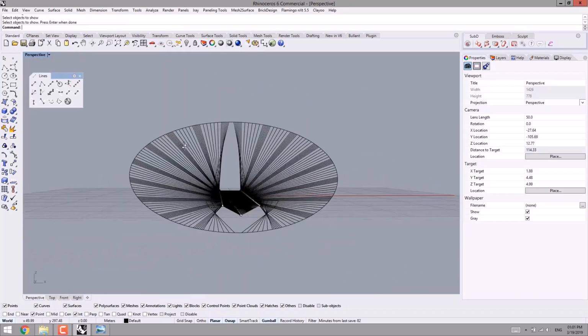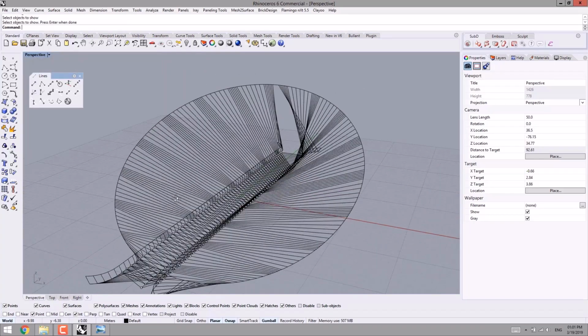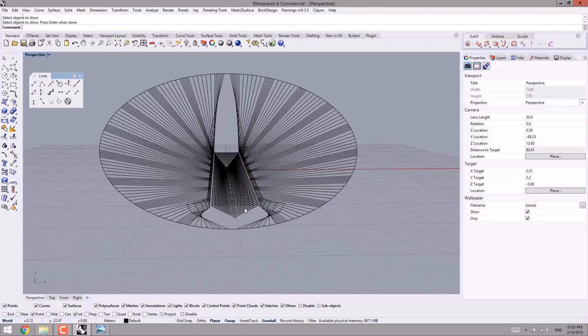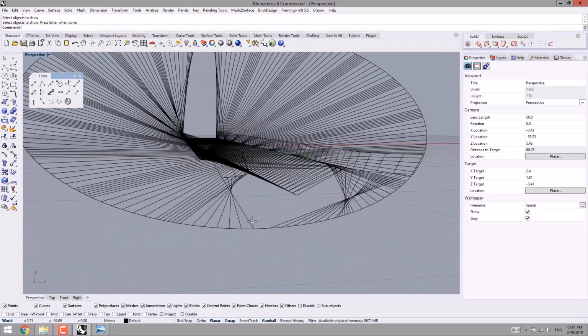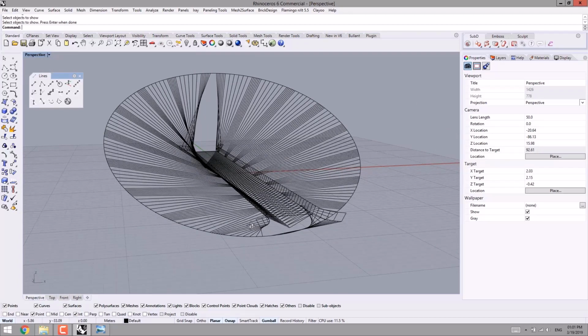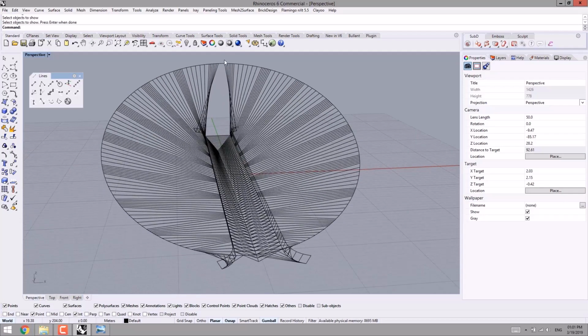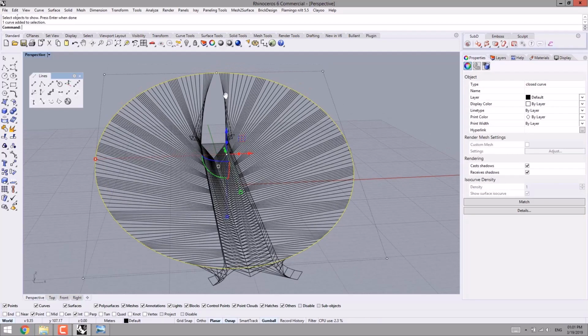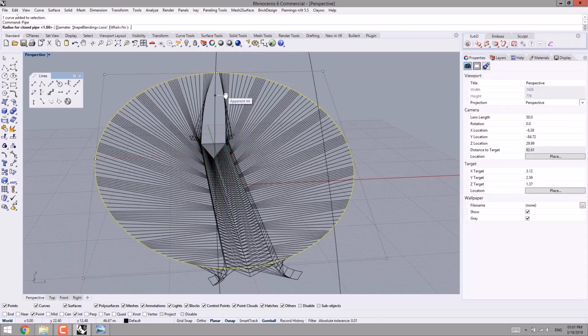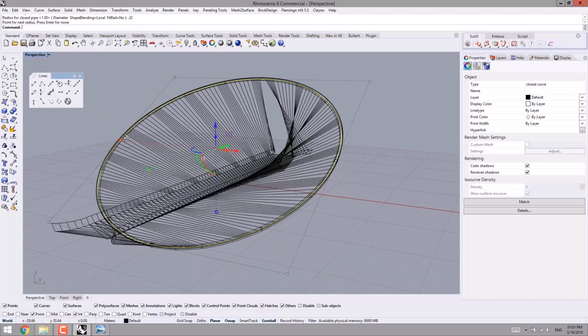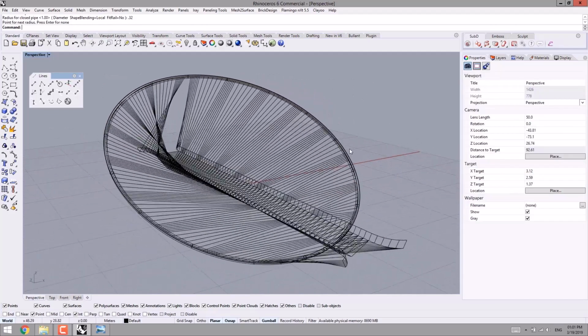Check this out. So till now, as you are watching the scene, we have completed the skeleton of the project or the model by this way, and in the continuation I'm gonna specify the desired thicknesses for each of the parts of the bridge by using the command of pipe. Firstly, I select the main circle, then I start the command of pipe. I should specify the radius for it, 32 centimeters for example. Then I apply it. Check this out.